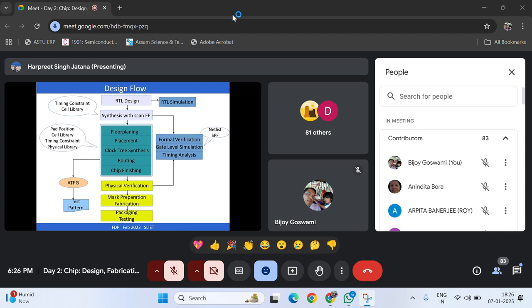So this is basically the design flow and the technology files which are used, because any design has to be made at a particular technology node. So you need the technology files, you need the physical library, the layout, what are the different layers used in a cell. You need the IO pads, which are normally supplied by the foundry. You cannot design an IO pad because the process is involved in there, because there are big diodes.